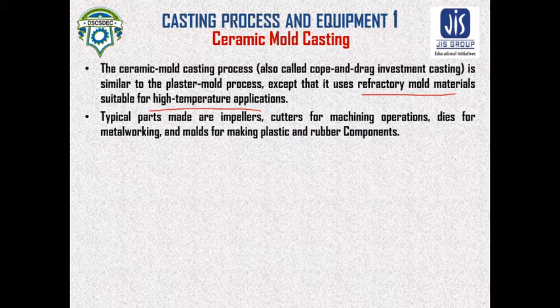The typical parts made using ceramic mold casting are impellers, cutters for machining operations, dies for metalworking, molds for plastic, and other rubber components.